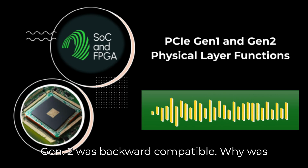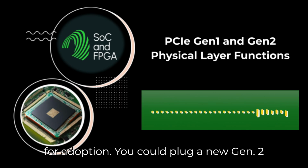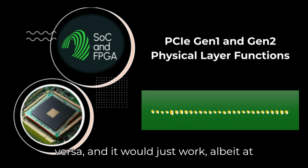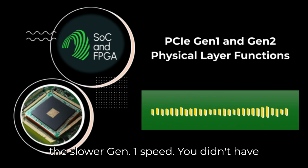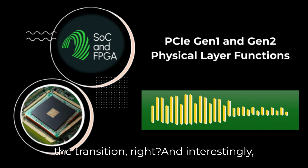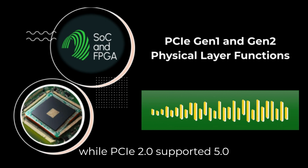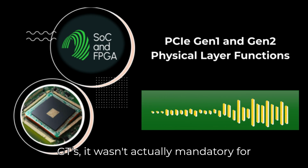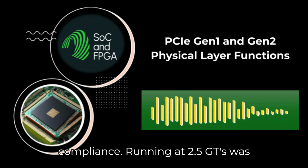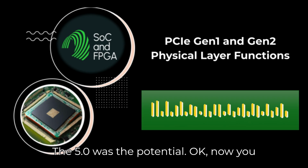And Gen 2 was backward compatible. Why was that important? Oh, massively important for adoption. You could plug a new Gen 2 card into an older Gen 1 slot or vice versa, and it would just work, albeit at the slower Gen 1 speed. You didn't have to upgrade everything at once. Smooths the transition. Right. And interestingly, while PCIe 2.0 supported 5.0 GT/s, it wasn't actually mandatory for compliance. Running at 2.5 GT/s was enough to be called PCIe 2.0 compliant. The 5.0 was the potential.